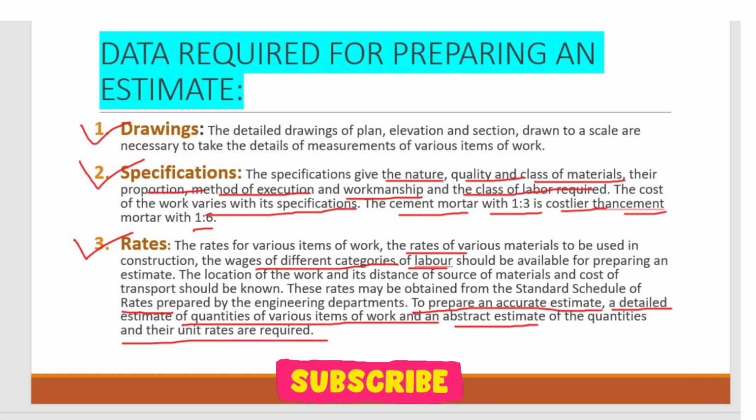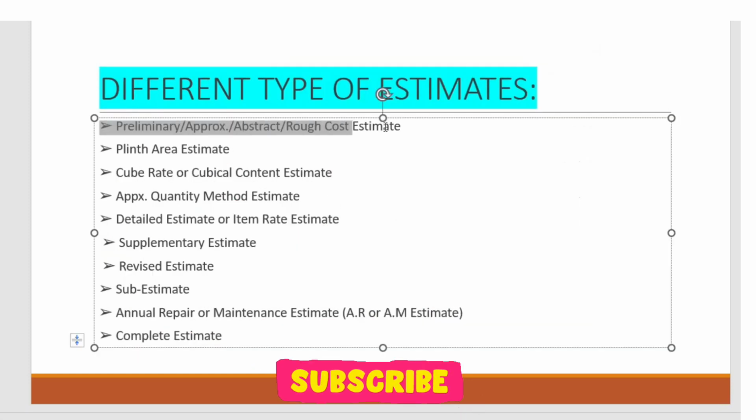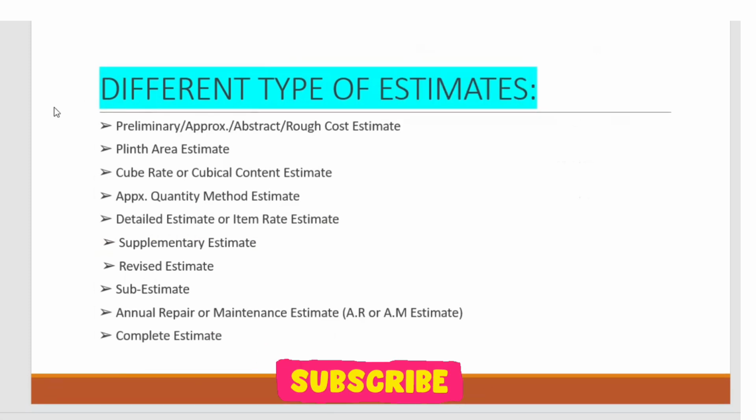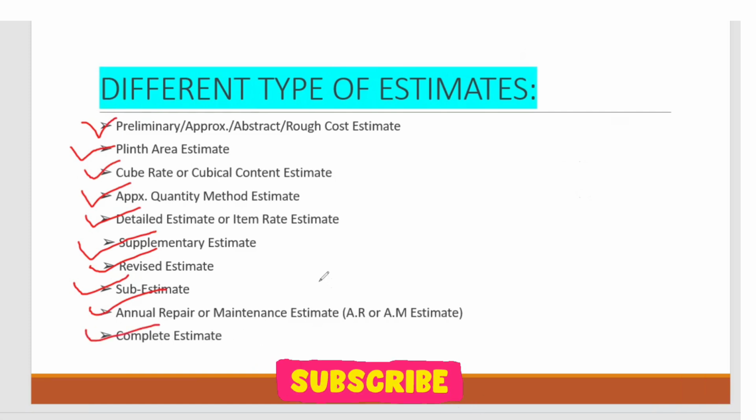Okay. Then the last one which we are going to discuss is types of estimates. So the first one is the preliminary estimate. Actually, broadly, three estimates are to be considered. That is the preliminary estimate, then the approximate estimate, and the detailed estimate. Then there are the supplementary ones, that is plinth area estimate and cube rate estimate, because they come under a certain category. The plinth area estimate, I think, comes under the approximate estimate. Then supplementary, revised estimate, sub estimate, annual repair or maintenance estimate, and complete estimate. So these are all the types of estimate. Broadly, we will discuss it in our coming tutorials.